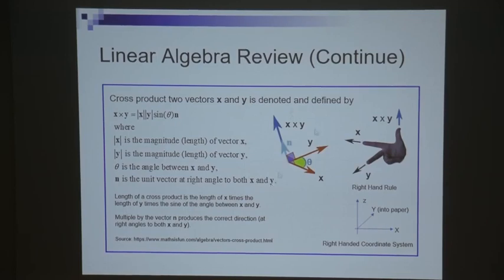So this is important because you'll be using something called a right-hand coordinate system. When you want to attach a frame to the base of your robot manipulator, you see that we draw the coordinate on the cube, on the cylinder. This frame, the x, y, and z, will have to be defined according to the right-hand coordinate system. Meaning that if I specify my x and y, my z will always be defined in this manner.